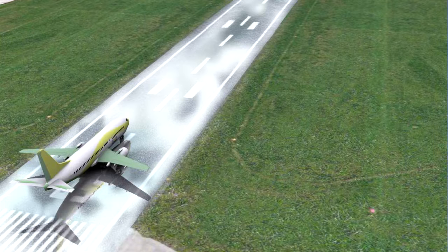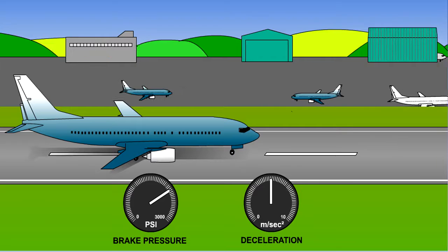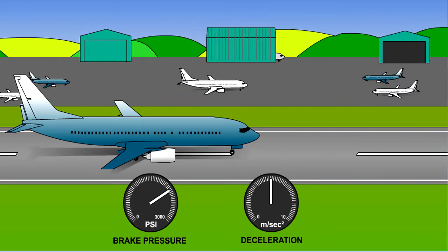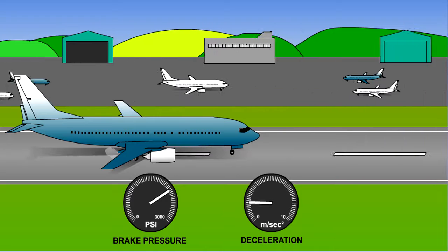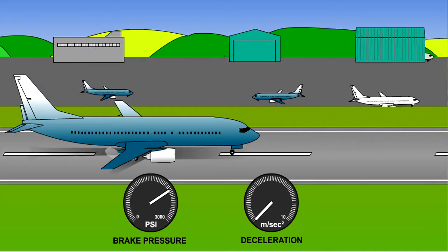The pilot is unable to sense when the wheels lock, and so the primary requirement of a brake modulating system is to provide skid prevention. Whenever braking torque is developed, there must only be a small degree of slip between the wheel and the ground. A skidding wheel provides very little braking effect.